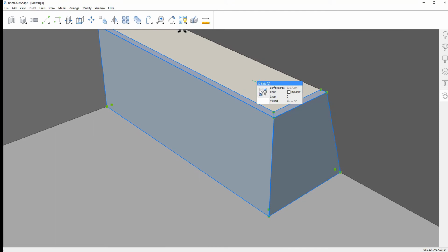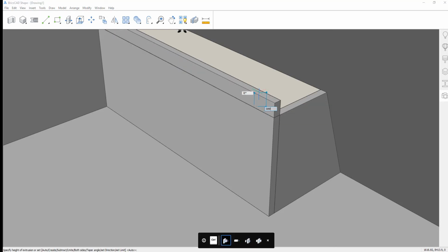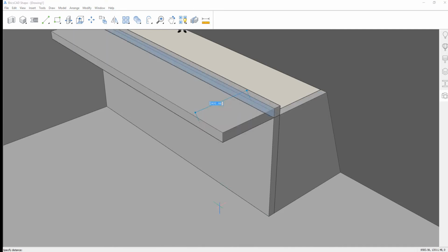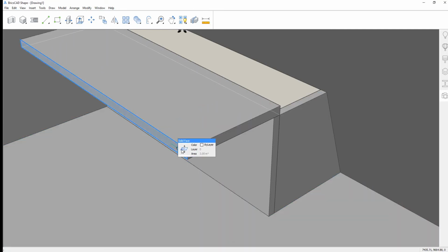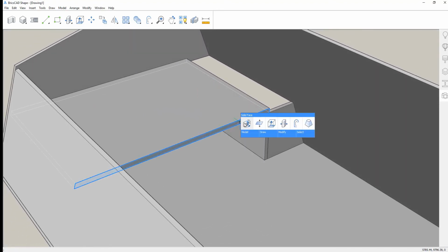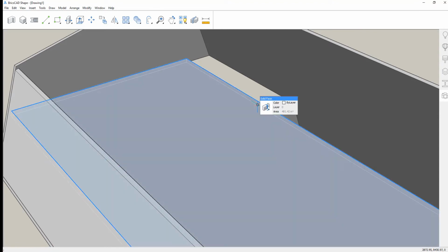Hiding the visibility on the roof, it's easy to change the way that these wall segments come together, bevel or butt. By using butt, we'll simply extract that top profile and create the floor slab for the first floor. Again, we'll drive those edges to the next solid face, and our floor is done.